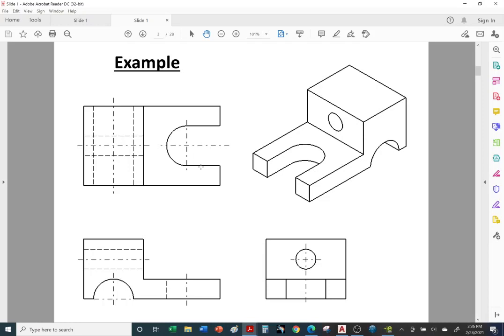We're gonna follow the same process for AutoCAD, just like the views lined up. So in chapter 1, we sketched our 3 views. Everything has to line up, right? So when we create our front, top, and side view, we're gonna do something similar as the isometric view. For the isometric view, we created a box. For our front, top, and side views, we're going to use rectangles. So we start with rectangles.